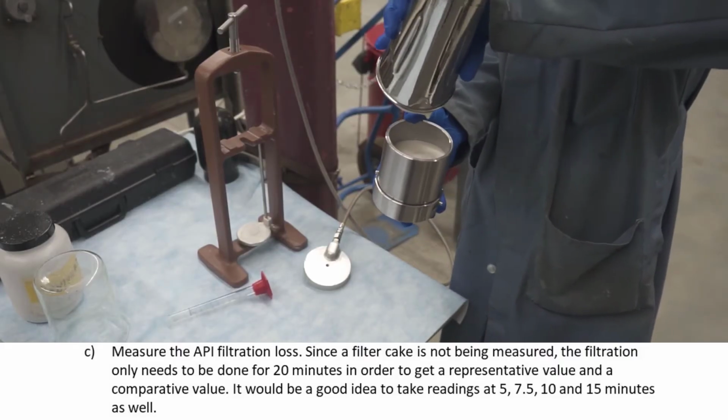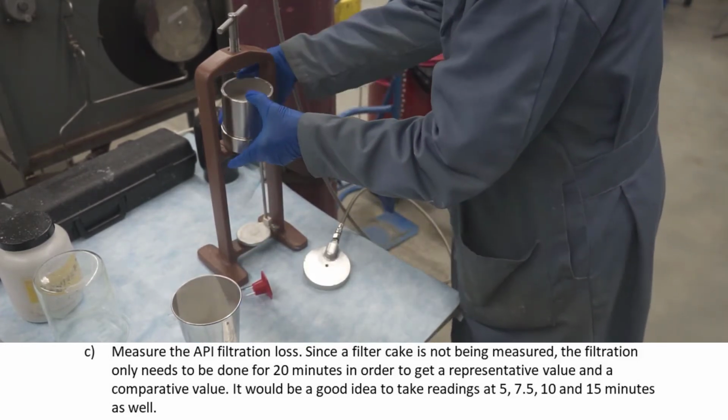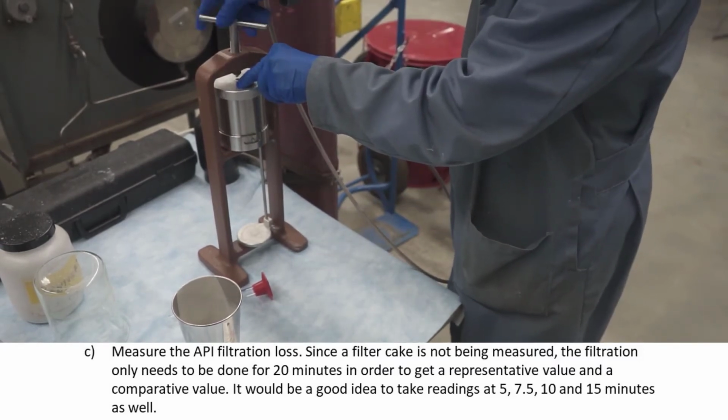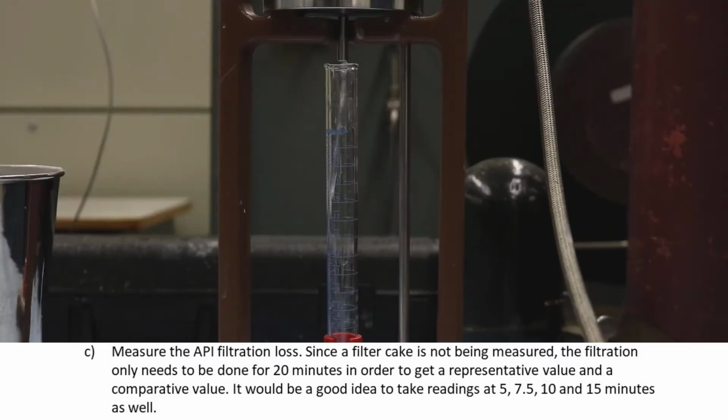Then measure the API filtration loss. Since you're not measuring a filter cake, the filtration only needs to be run for about 20 minutes. Take readings of 5, 7.5, 10, and 15 minutes as well.